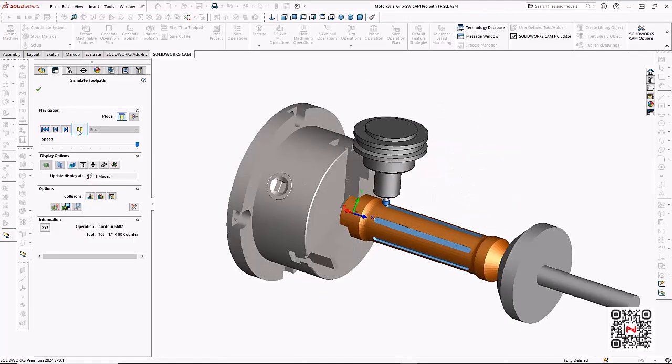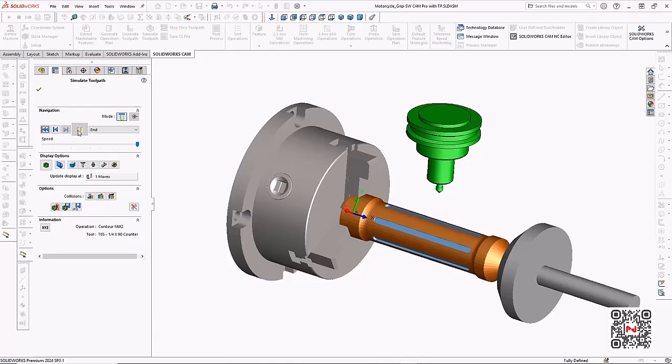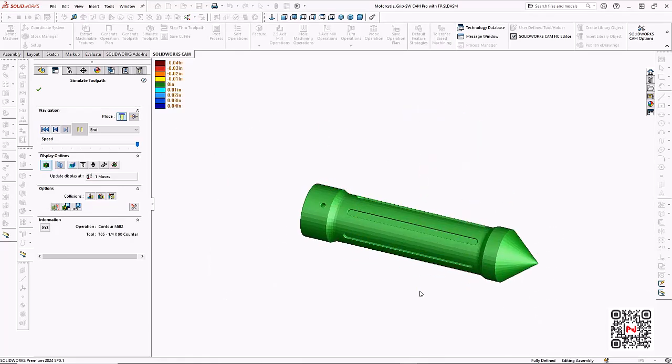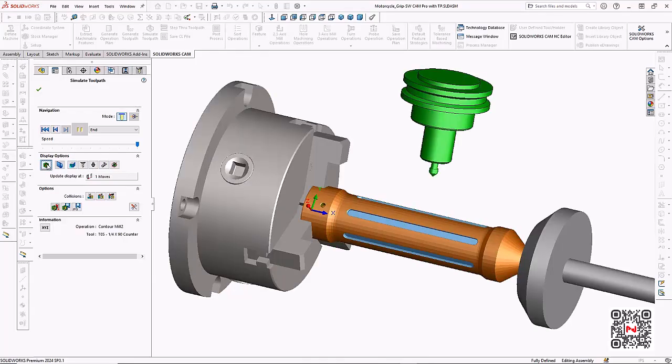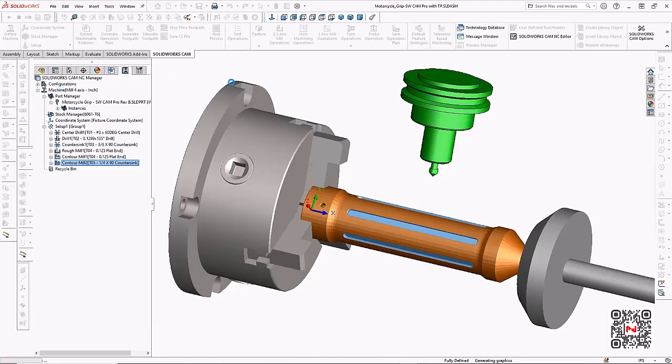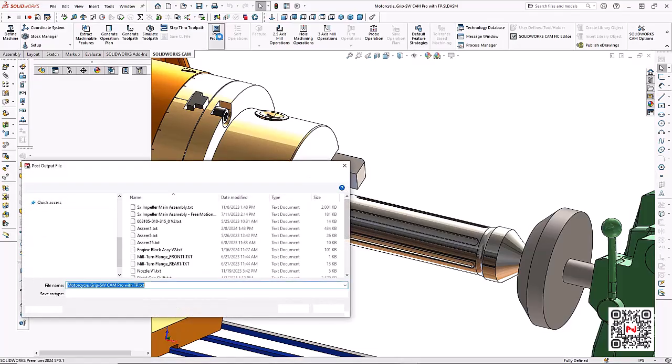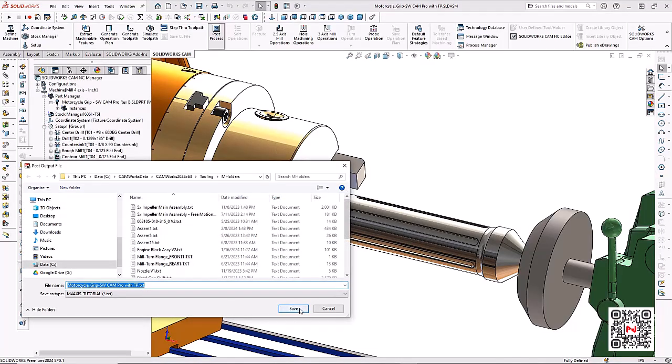And you can see now that that holder cleared and the collision did not occur. And then we can compare the machined model to the design model again, and we can see everything is in green. So it's been machined nicely net to the design. And now we could go ahead and post-process the G-code file for the 4-axis mill.